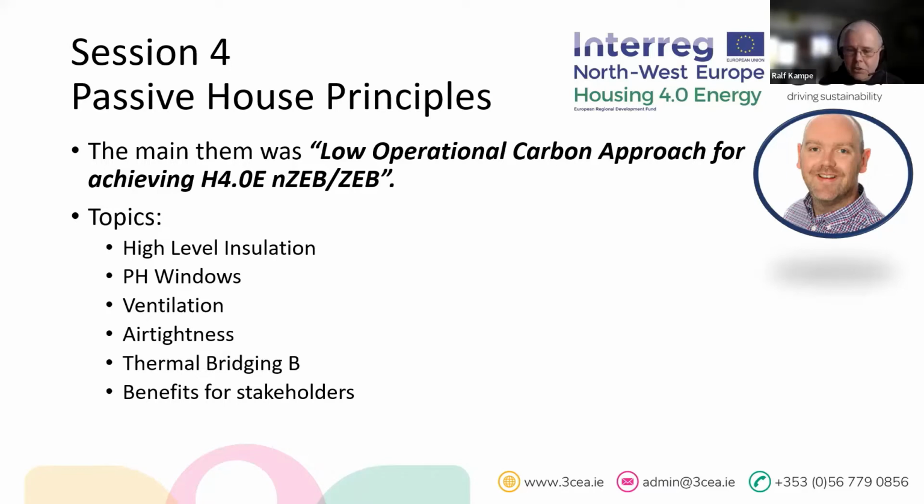They have a rough number of 200 mil and not more for insulation, and PV windows, with different sizes and different glass specs for different orientations, and ventilation for heating, fresh air, and heat recovery, and air tightness.